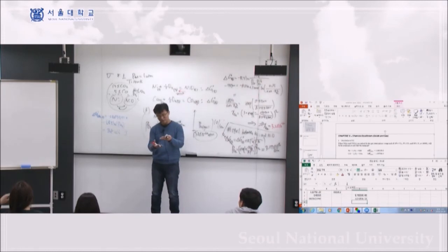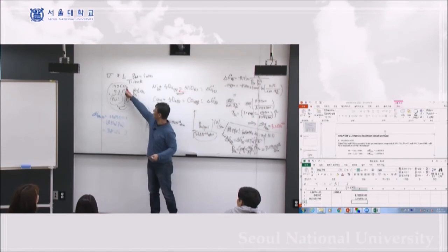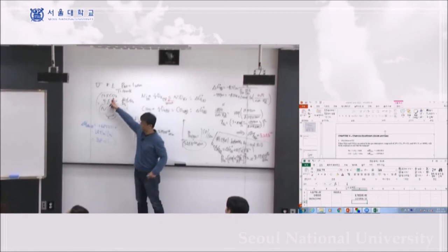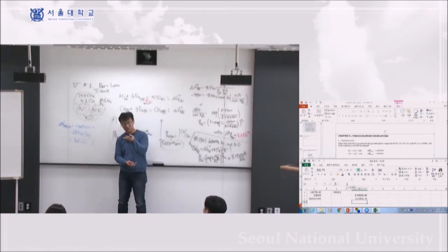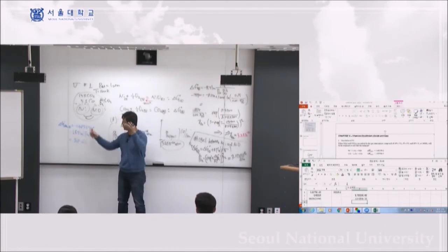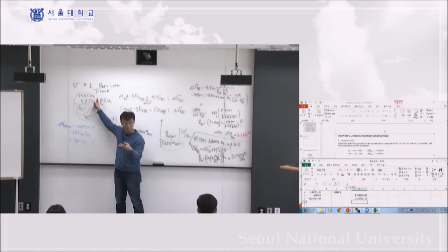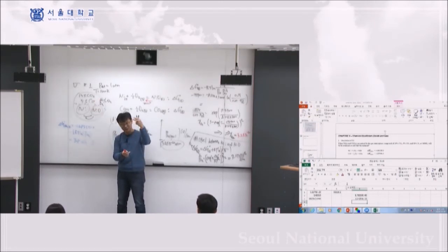I'm not asking you what's the final state, yeah? I'm just asking about the beginning. So in the beginning, I should maintain the same value. So now I have 15% of CO2 and 5% of CO in the gas phase. Just the beginning. And then I'm adding nickel and nickel oxide inside of that gas phase, and I'm asking whether the reaction is going this way or this way. So I haven't changed my CO-CO2 ratio yet. So this is my current state. According to my current state, is my chemical reaction going this way or this way?